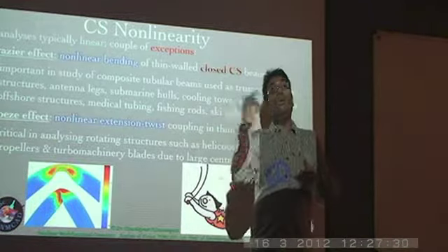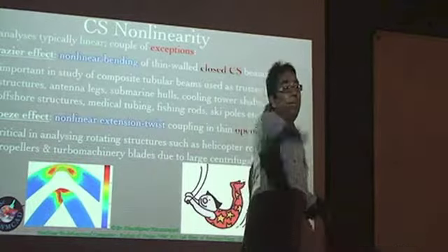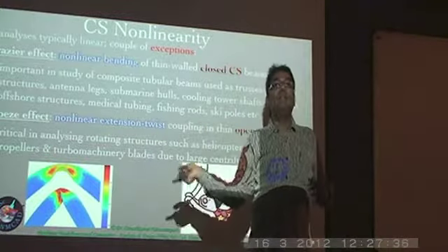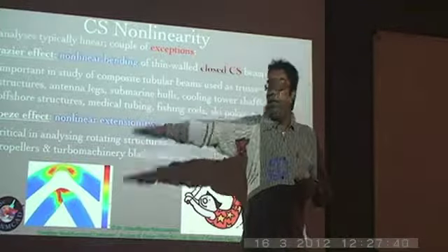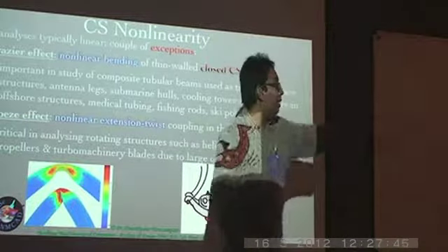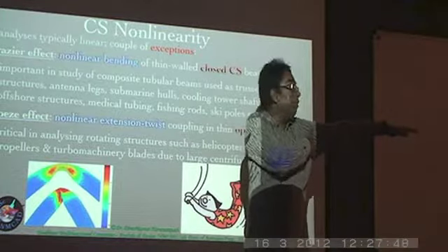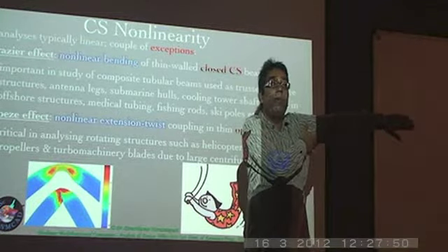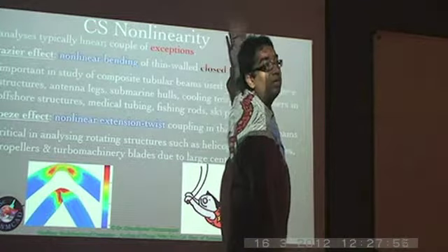In other words, aerodynamically speaking, the twist and the bending are coupled to each other, but they have a 90-degree phase lag. So if I make the pitch minimum here, I get the minimum bending over here. Similarly, when the rotor blade comes to this particular location, if I increase the angle of attack to the maximum, then at this location I have the maximum upward bending.